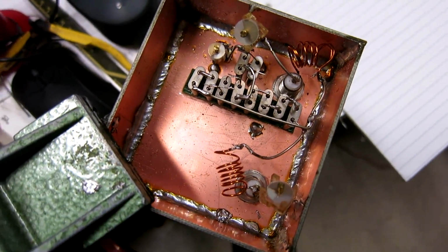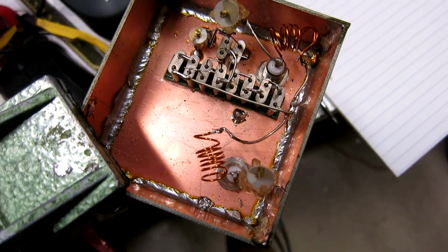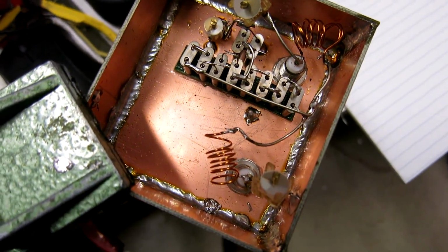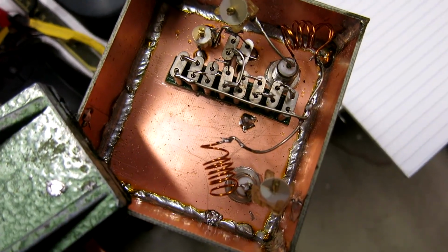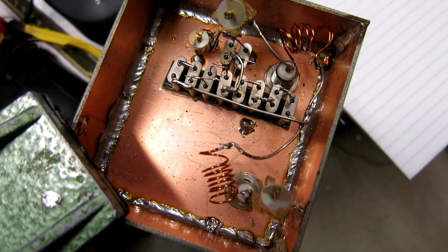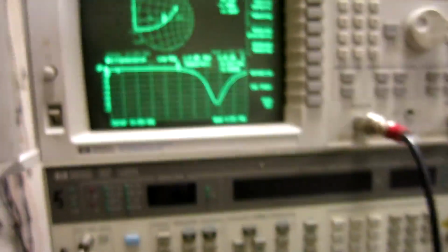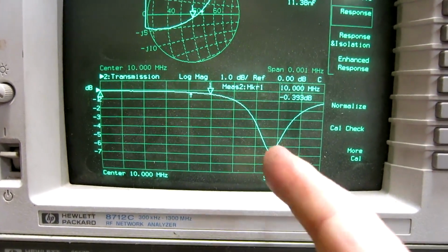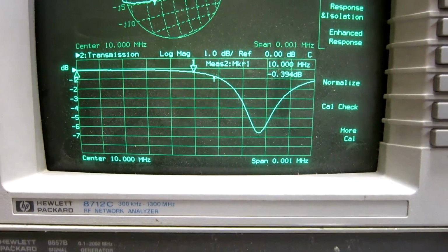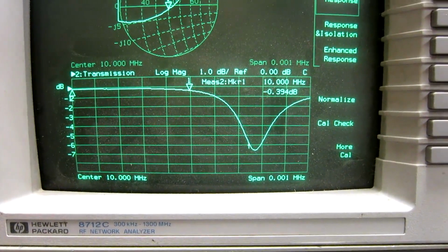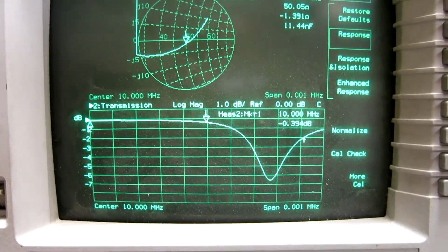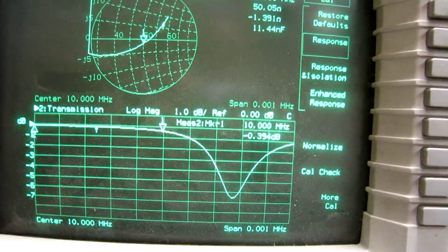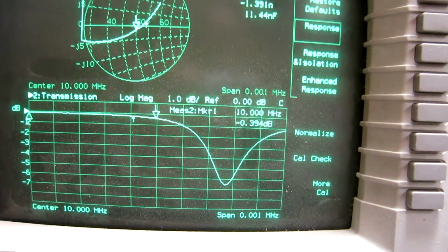To make sure that the unexpected result is not caused by my test system, I have made this filter to remove part of the noise on one side of the carrier. It looks like this. It's an offset of 270 Hz or so. The impedance is accurately 50 ohms in both directions, and the loss is 0.39 dB.